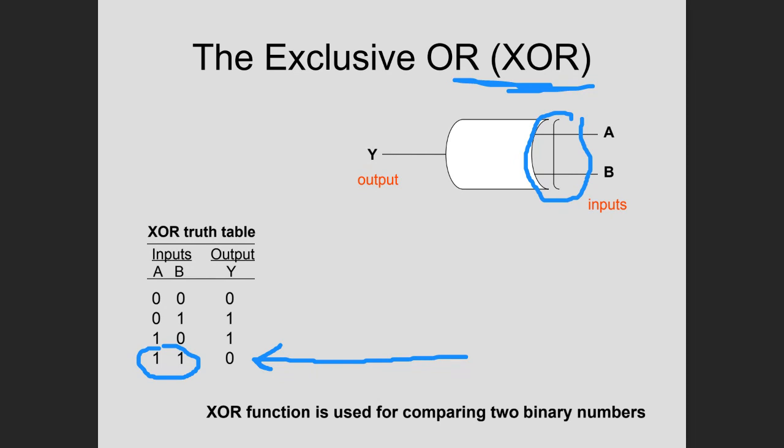And so what we mean here is that when we want to make sure we have two or more events, we want to make sure something's not happening. We can do that with what we're going to call software interlock. And if you look at the truth table, you can use this kind of logic to make sure that if I have two or more events, and we'll just focus on two events, they don't happen at the same time.